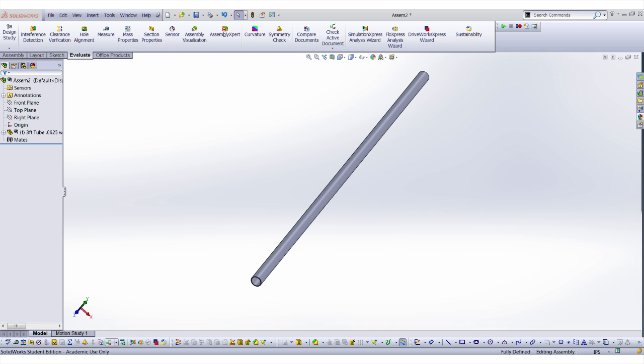It's a good habit to start making parts that are real. So in real life, you wouldn't be able to take a 1-inch pipe and put it into a 1-inch hole. It doesn't work. It's very, very difficult. But a 1-inch pipe into a 1.003-inch hole is actually reasonable, and you can press fit that, and it'll actually work. So if you were laser cutting stuff, you can actually do it. So figuring out what your dimensions are and things is useful.